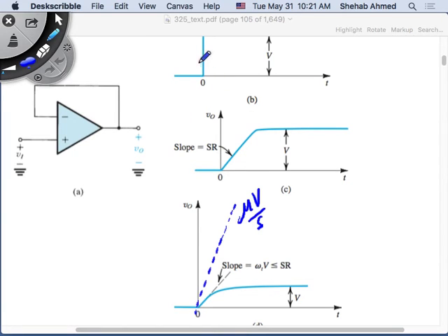No. This step waveform was rising infinitely fast at the input. So at the output, let's say you have a unity voltage follower, a unity gain amplifier, what do you expect to see? You expect to see what you have at the input. Is it going to rise infinitely fast? No, because of the slew rate. This op-amp has a maximum rate of rise of voltage per second. So here your step waveform was limited because of the slew rate, and now it was distorted to look like this.